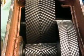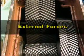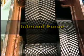An overload which causes a break may have been caused by forces external to the gear set, or it may have resulted from an internal force. It's important to be able to tell the difference between external and internal overloads because you'll deal with each type differently. Let's first discuss how internal overloads develop and see how to identify them. An internal overload starts when a gear tooth breaks due to fatigue failure as shown here. Then the adjoining teeth are overloaded as the mating gear teeth jump across the gap left by the missing tooth. This may cause the adjoining teeth to break.